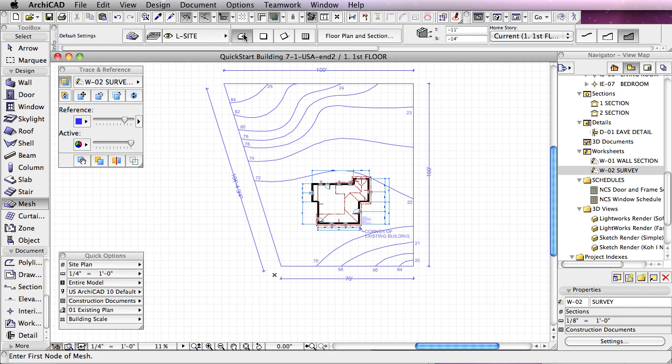And remember, I'm in the polygon mode, so I can click on a corner, and then another corner here, and another corner, and another corner. And if I want, I can go back to the first point, or I can click on this point up here, and it will close it. Because it has to be a closed shape, it will return. Now, if I select it, and I can do that by holding down the Shift key to get the arrow and clicking it, you'll see that we've got this thing selected.